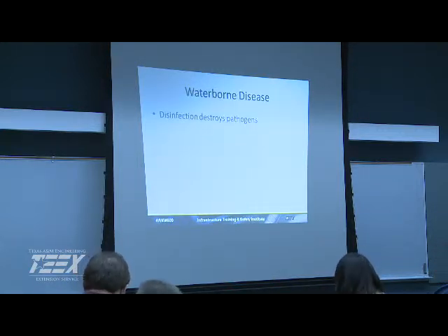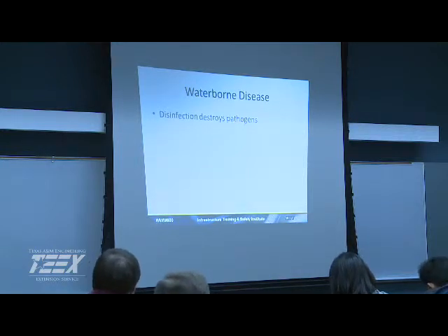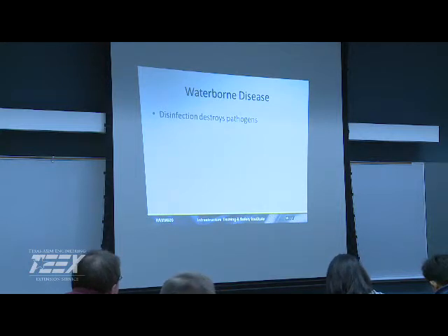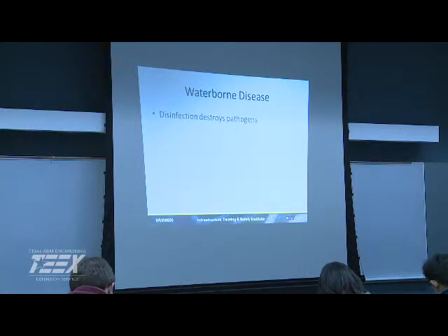Waterborne diseases. Why are we wanting to disinfect our water? Got to get rid of the pathogens in there. Again, you can have pristine water coming off your lake, something like that. You're still going to have potential contaminants with waterborne. And surface water treatment actually looks a lot at how much crypto you actually have in there. That's going to be your bin classification. So what does your source water look like? That's a real important component of it.